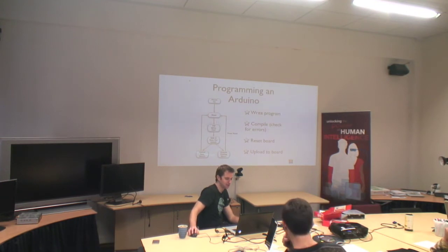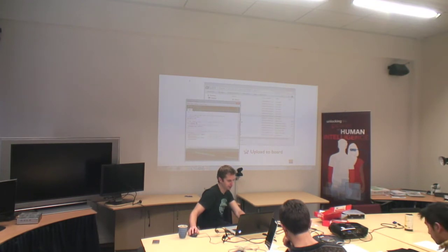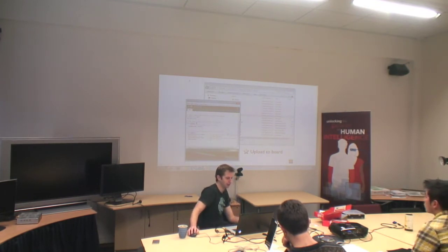But yeah, pin 13 blinks fast, and then you can upload a new sketch. It says here wait 5 seconds for upload, but you don't actually have to do that anymore. You can upload at any point in time. So even while I'm midway through running my sketch, I can upload a new sketch while it's doing its thing.